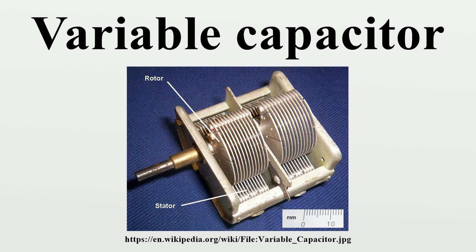Their use is limited to low signal amplitudes to avoid obvious distortions, as the capacitance would be affected by the change of signal voltage, precluding their use in the input stages of high-quality RF communications receivers, where they would add unacceptable levels of intermodulation at VHF, UHF frequencies, e.g., in FM radio or TV tuners.